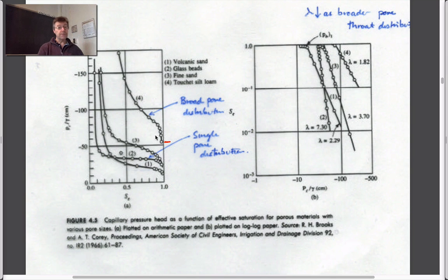We know from what we talked about before that, because the entry pressure is high relative to this, this is probably a lower permeability, with smaller pore sizes than this one, which would have more open pore sizes. We know from the shape of these curves that for this one, basically all the pore throats would be roughly the same size, because once we've invaded the first pore throat at this bubbling pressure, it fills up all the other pores within the system.